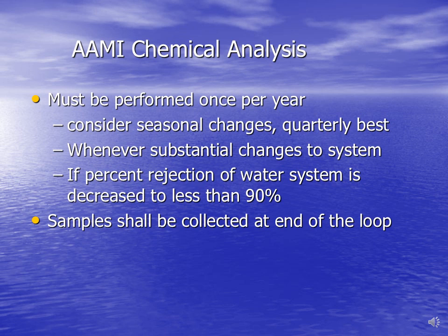the sample shall be collected at the end of the loop. End of loop, because if there's work in the piping system ahead of the end of loop, and you were to test at the beginning of the loop before the repair job that introduced leachable substance, you'd never pick that up.